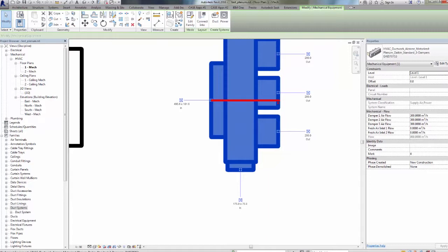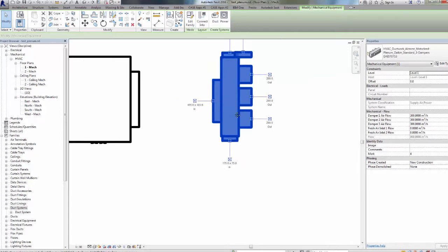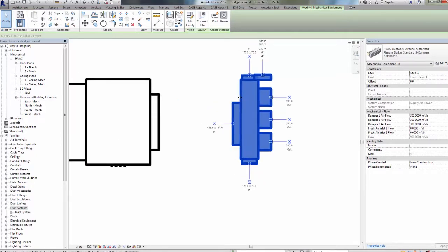In the plenum, there will also be both a connector and the plan that coincides with it. It is necessary to be careful with some plenum configurations, because here there is another reference plan to align the ducts with the dampers. These two plans shall be very close, and sometimes it may be better to eventually modify the gap of the neck with respect to the side, in order to have the plan displaced, then relocate it and restore this gap.